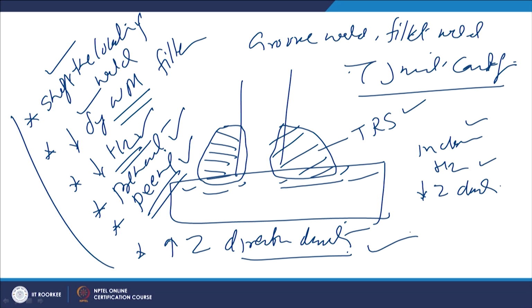So, these are the two most common types of problems which are encountered during the welding of carbon and low alloy steels. Now, I will summarize this presentation. In this presentation, basically I have talked about hydrogen induced cracking, the various factors that promote hydrogen induced cracking and what can be done to control it, and thereafter another commonly encountered problem in welding of carbon and low alloy steel, that is lamellar tearing. What are the factors that contribute towards lamellar tearing and what steps can be taken in order to avoid or reduce the tendency of lamellar tearing.